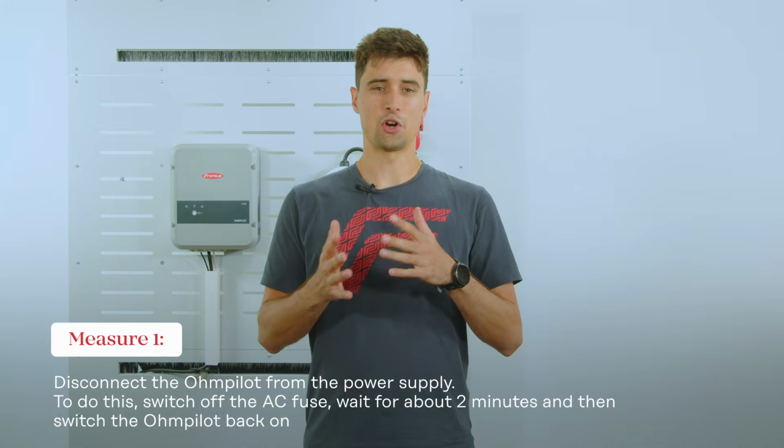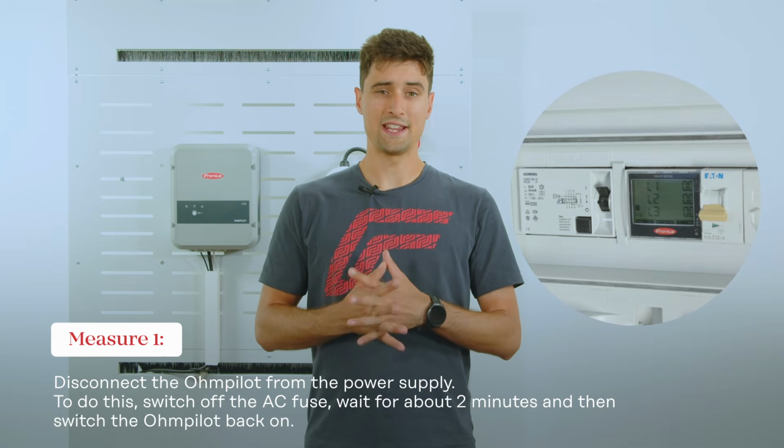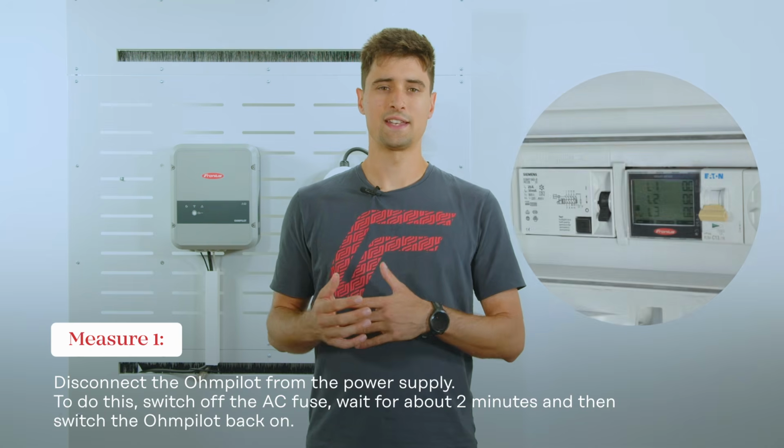Secondly, let's go to the easy wins you can do. So measures that can easily be taken and that already might be helpful. First of all, switch on and off the Ohmpilot. In order to do so, switch off the AC fuse, wait 2 minutes and then put the Ohmpilot back on.